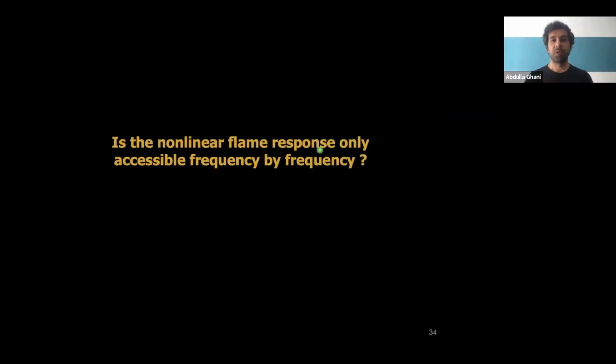But there's one specific question now, because I just said system identification is coming from control engineering, and it's restricted to linear systems. Basically, it assumes that your system is a linear time invariant system. And once we talk about nonlinearity, you're not anymore linear, right? So we know that system identification for the nonlinear flame regime is not working. And what are now the different methods that we could use to assess from the CFD point of view this kind of nonlinear flame dynamics?